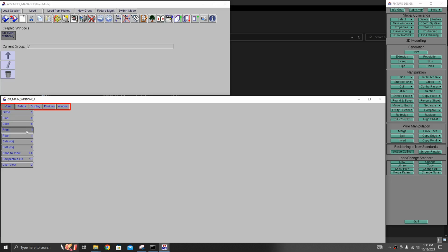In Fides, if you turn on the caps lock and press P, some option will come, and if you press the small letter p, a different option might come. So there will be both options, so be aware of that. You should always press small p for plan view.